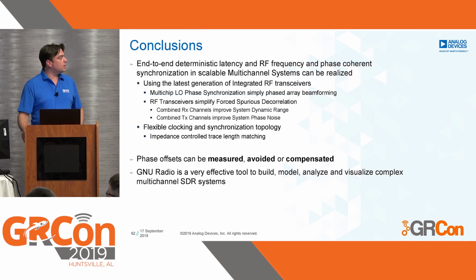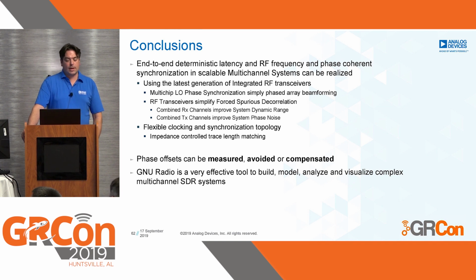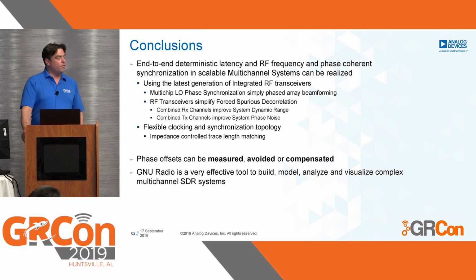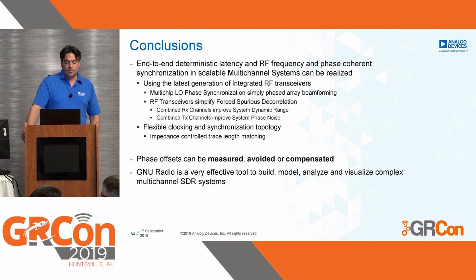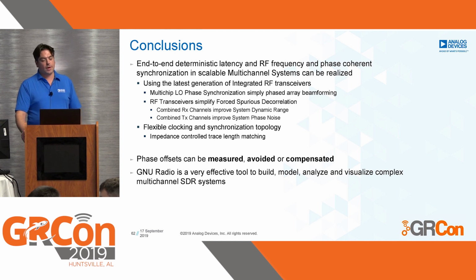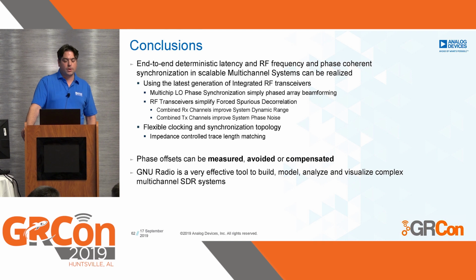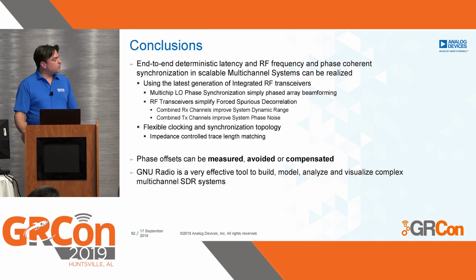So what are the conclusions? End-to-end deterministic latency in RF phase and frequency synchronization can be realized in a multi-channel system using the latest generation of integrated transceivers. The multi-chip LO phase synchronization simplifies phased array beamforming. The spurious free decorrelation can improve your system dynamic range and also your transmit phase noise.